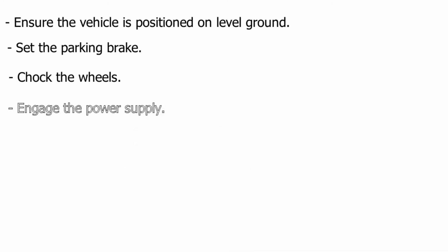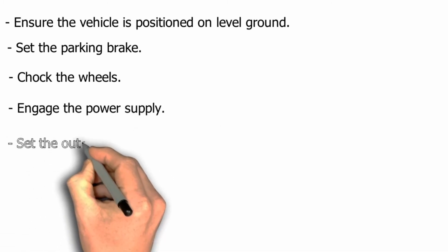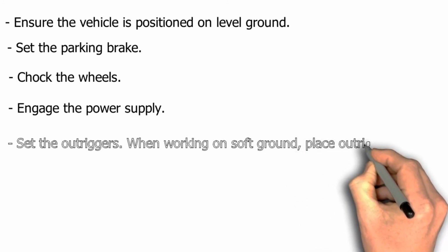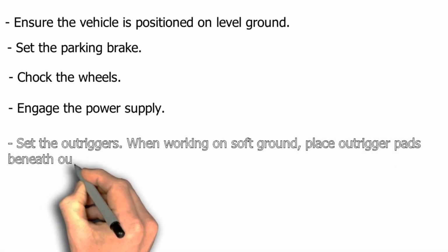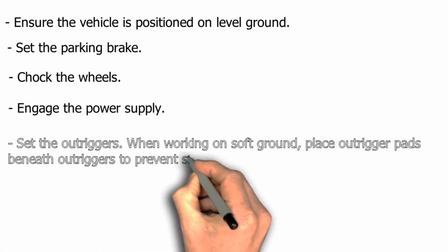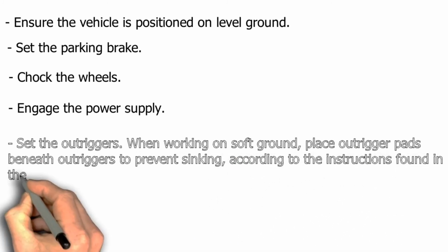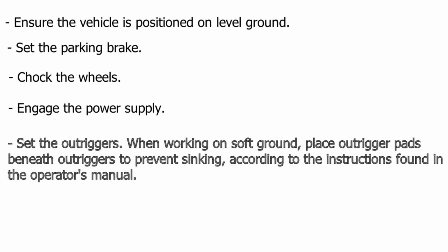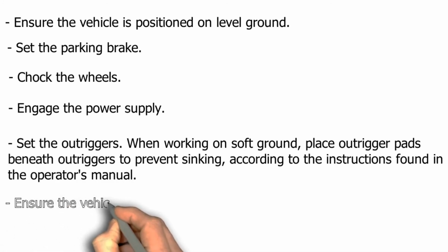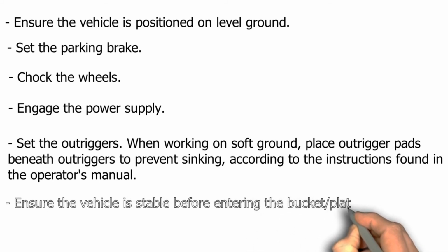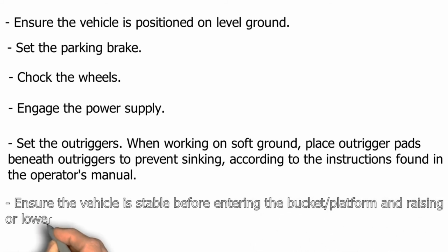Engage the power supply. Set the outriggers. When working on soft ground, place outrigger pads beneath outriggers to prevent sinking, according to the instructions found in the operator's manual. Ensure the vehicle is stable before entering the bucket or platform and raising or lowering the boom.